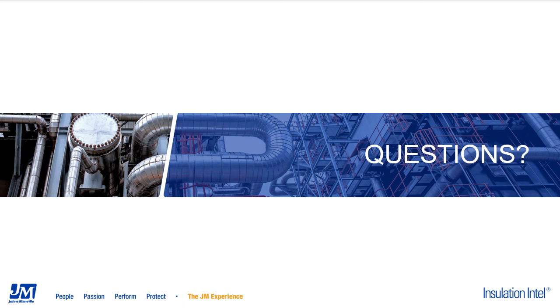I'll be honest, I hear the words emittance and emissivity used interchangeably in the industry. I'm sure some PhD physicist can tell you the difference between them, but for our purposes, emittance and emissivity can be considered synonymous. Stainless steel has an emittance or emissivity of about 0.3, and that is for all wavelengths of radiation, not just UV. That's its total across the board emittance for a wide range of radiation wavelengths.